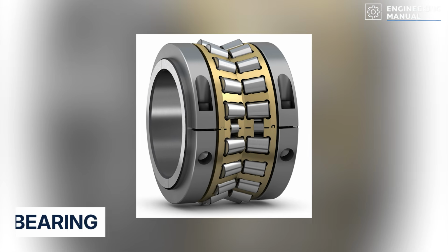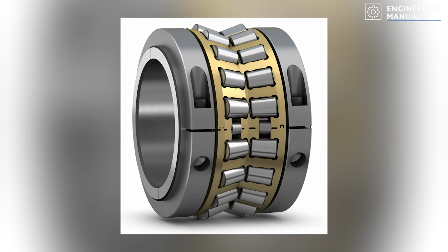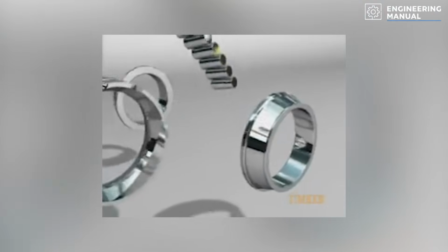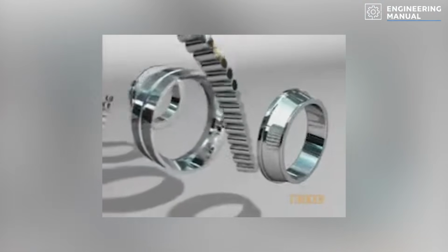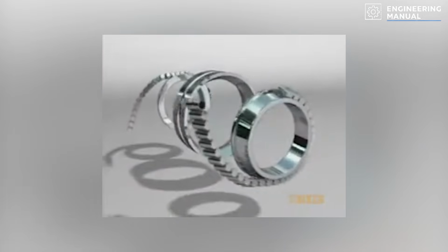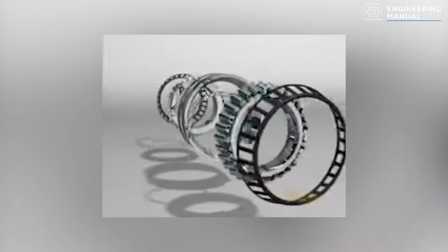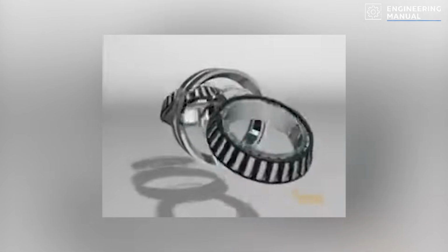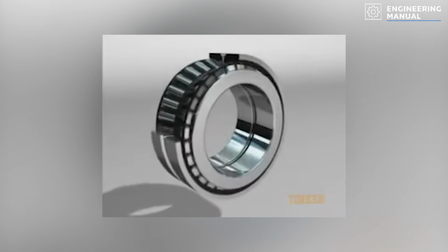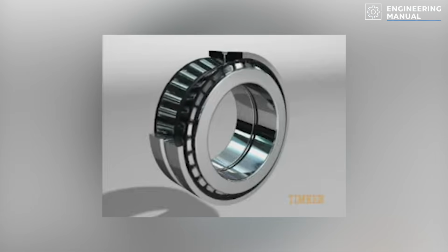The answer was to reshape the rollers. Instead of cylinders, they became cones. The raceways became tapered as well. If you extend every tapered surface inward, they all intersect at a single point along the shaft's center line. That geometry is remarkably elegant. Every roller now rolls naturally along its raceway while simultaneously carrying both radial and axial forces. The bearing no longer fights axial loads, it expects them.